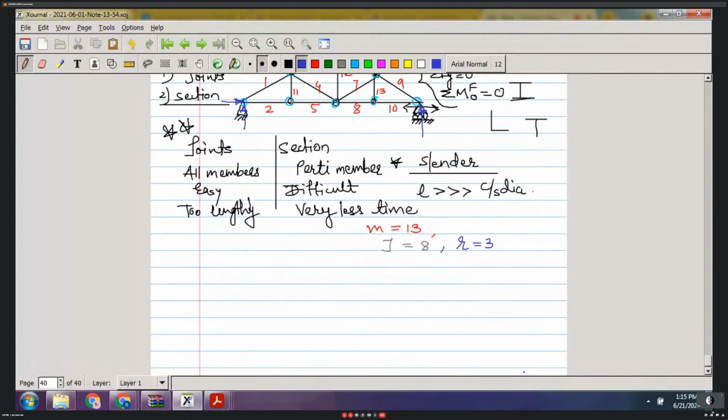Yes, ma'am. Okay, so there is one equation to check whether the truss is a perfect or imperfect truss. It is the equation M equals 2J minus R, where R depends on the type of support. These two you can easily calculate just by looking at your truss. Members are 13, joints are 8, and in this case reaction components are 3. So 13 is balanced by the right hand side, 13. Is it clear?